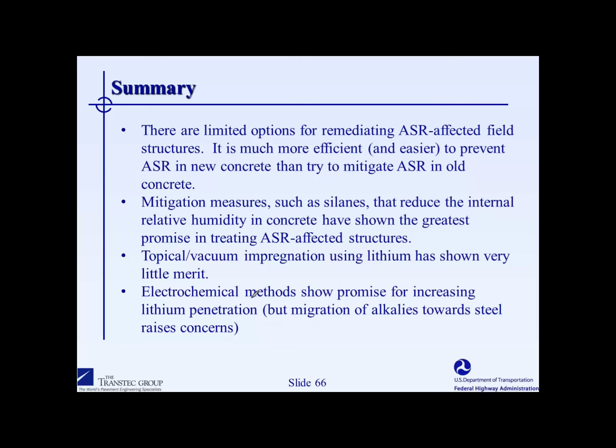Okay, excellent. The next question is, what technique did you use to quantify lithium? What we did, in terms of the profiling, is take cores from the field back to the lab. Then we would surface grind the concrete 1 millimeter at a time, the same way people typically do for determining chloride diffusion.